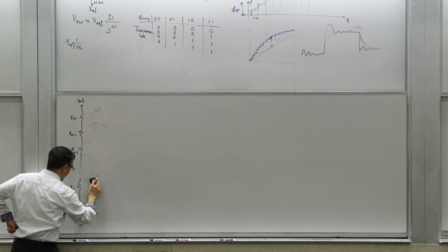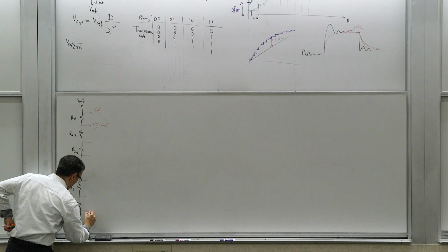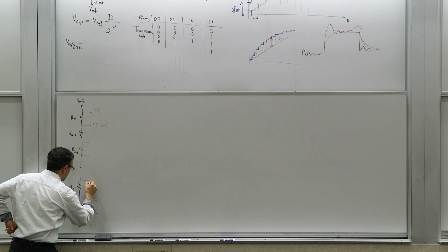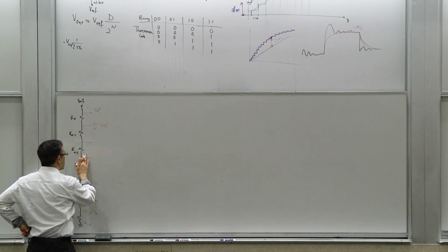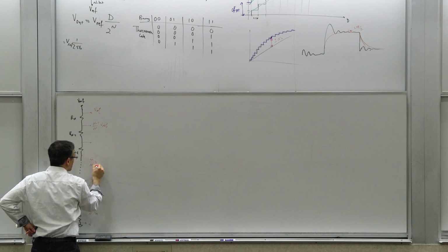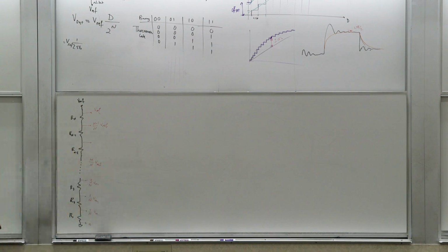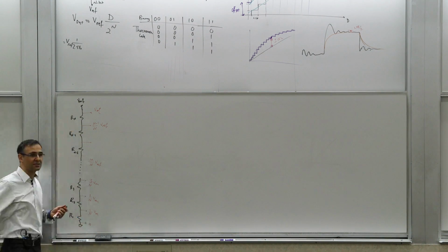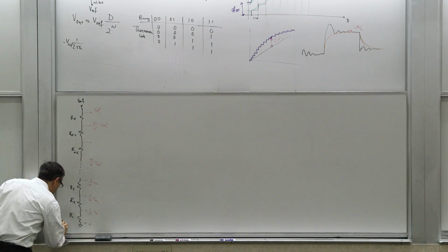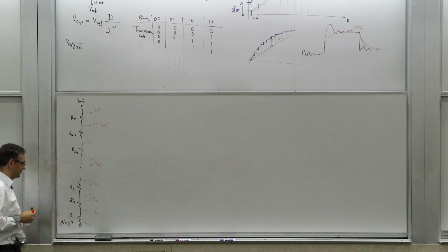I should have probably written it that way, that's a better way of writing it: 1 over N Vref, 2 over N Vref, 3 over N Vref. Somewhere in the middle, I have M divided by N times Vref. So we have generated all the voltages that you can possibly want off of this ladder. If you are making an 8-bit D to A, this has to be 256 resistors, by the way. So this N is really capital N, which is 2 to the power of N.